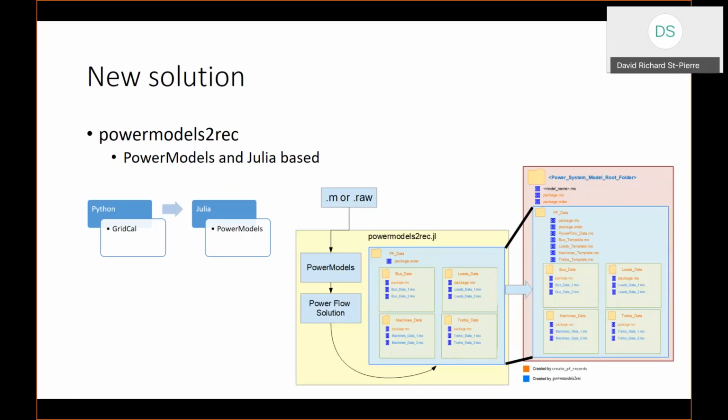These files contain information about the bus structure, the different generators that are on it, and the transmission lines, etc. The .m file format is a special format specified by the MatPower specifications.